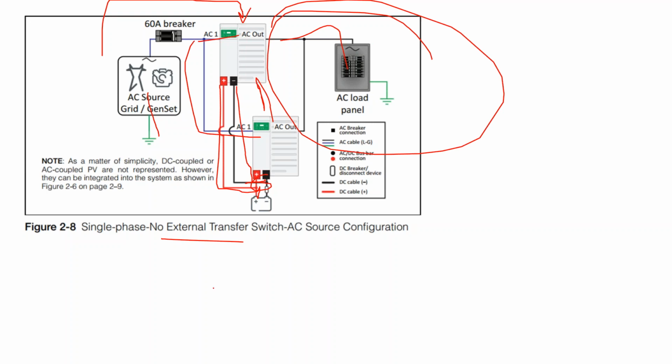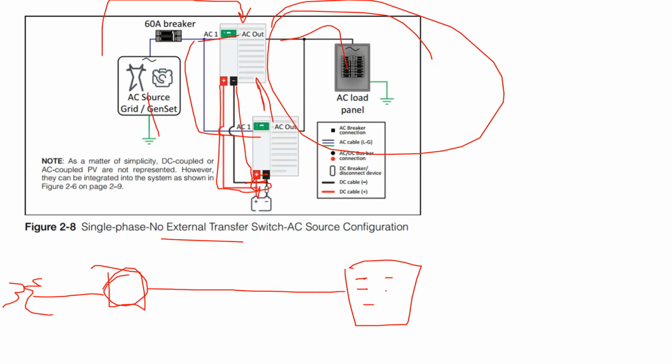And so where these inverters would want to be landed in order to do this is you have your utility meter coming in from your grid connection, and then you have your home load panel. And usually, for residential, you're tying in the solar array onto the bottom of the bus bar on your breaker panel. But where this would be tied in, in order to take advantage of the transfer switch built into the system, is halfway in between. So that's a supply side connection or a line side tap.